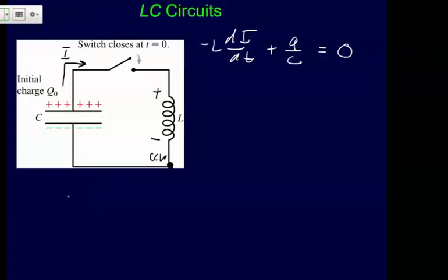And so typically, when you get to these more complicated circuits, what you do is try to break these down into a differential equation. This is probably real similar to stuff you did with a mass on a spring. So the first thing we're going to say is that the current is going to be negative dq/dt. The reason it's negative is because your charge is going to be leaving that capacitor. When we talk about Q, it's how much charge is on that capacitor. So in this case, as the current moves away from here, you're going to be reducing that Q.